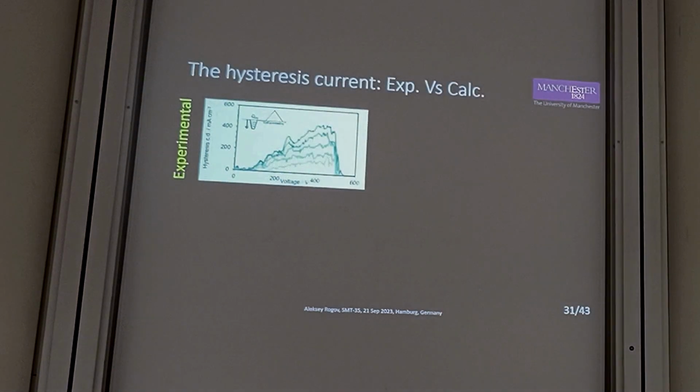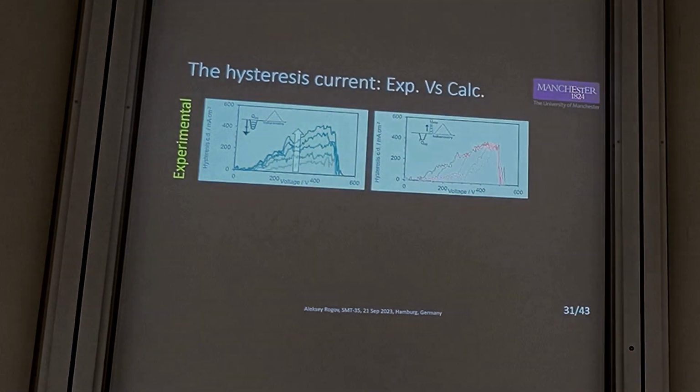And what shows the experiment? If we apply only negative pulse, following triangular pulse shows characteristic response. So the higher the negative pulse, the higher the hysteresis current within the same voltage range. However, if we apply additional positive pulse between negative and diagnostic pulse, what we will see in the diagnostic pulse analysis is that increase in positive pulse reduces the hysteresis current, or hysteresis charge, indeed, but it happens in an absolutely different manner, by means of change in the threshold voltage.